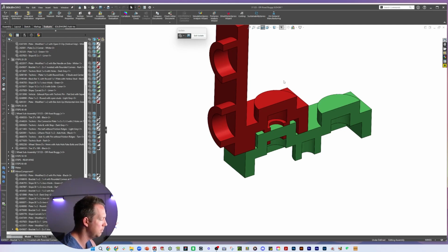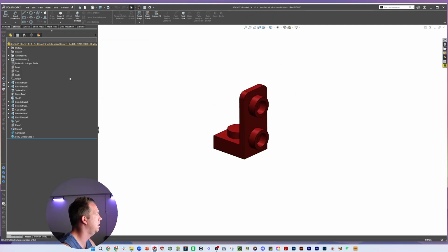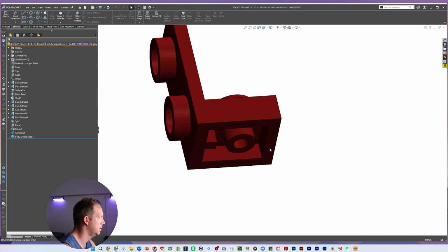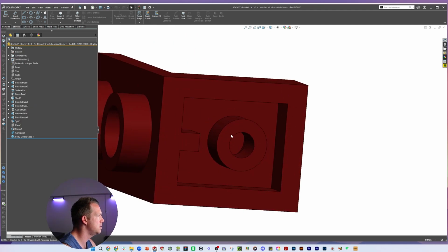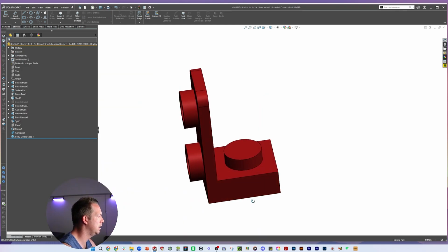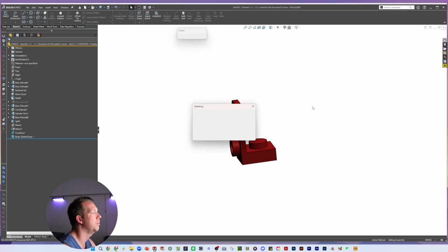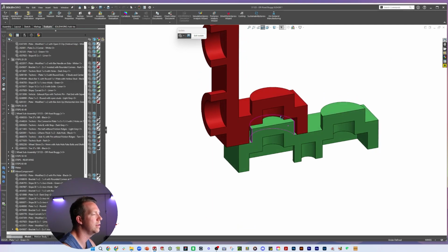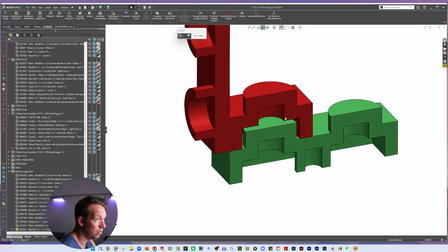Okay, well, I've definitely made a mess of my little model. And I can also see the problem with this file here. It's this one. Now, this was an inverted part, but there is no extrude here. So if I suppress that, that now looks correct. And save that, go back in, have a look, and now there's no interference. Okay, so it's helping us to identify the errors in our geometry, or sometimes it might be a feature that you have suppressed or unsuppressed accidentally or incorrectly that's causing the issue.